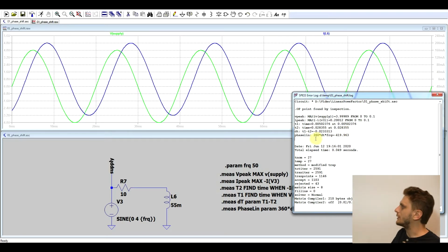So the main problem here is that for LTspice the waveforms aren't functions, but rather sets of points. So our peak voltage doesn't happen at every single peak of the waveform, it might happen only on a single peak, because of the way the individual points are measured. So we don't have a very big difference between the peaks, but since the two peaks are not one next to the other, we get this sort of behavior in which our time difference is more than a period.